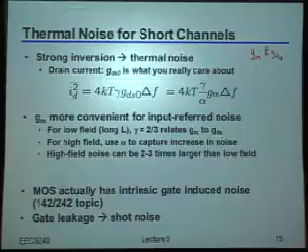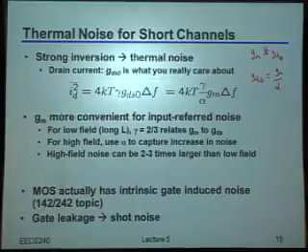Remember, the whole derivation we did was by relating GM to GDS naught and then knowing how much thermal noise GDS naught would have in the first place. Because those two are not exactly the same, people introduced a new parameter that said that GDS naught was equal to something like GM over, not gamma there, alpha. Okay? So that alpha factor is another proportionality constant between what GM and GDS naught really are, at least from the standpoint of thermal noise behavior.